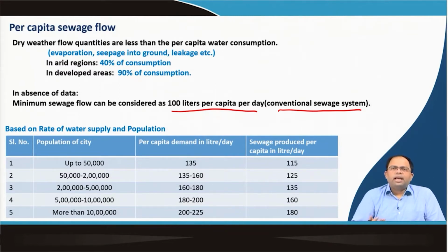If I go with that kind of assumption, then we would end up wrong, because in most buildings and real estate projects, they will have their own water supply systems, right. So at least we have to go with 100 liters per capita per day.